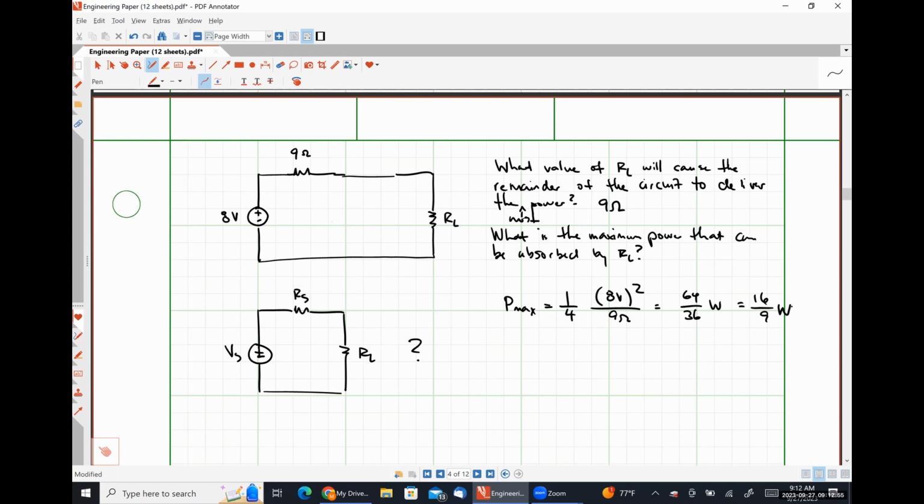And I might ask you how much power that resistor absorbs. And so the correct answer would be like V squared over R, I squared times R, and then depending on whether the current is flowing into the positive polarity terminal, it would be I times V. If the current were flowing into the negative polarity terminal, it would be negative I times V. That kind of thing. So reinforcing the passive sign convention and stuff like that.